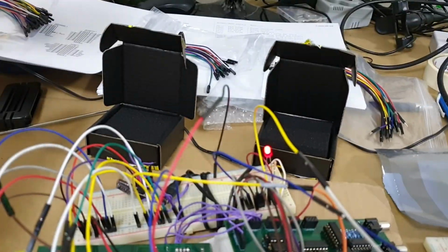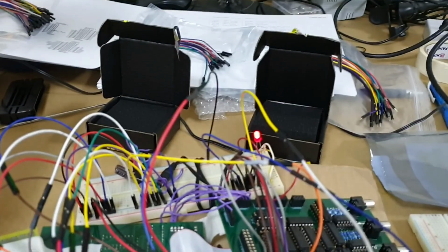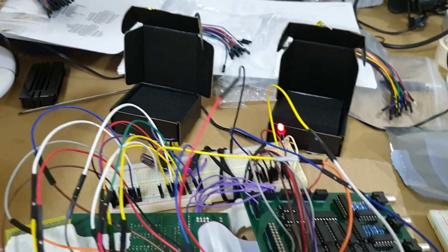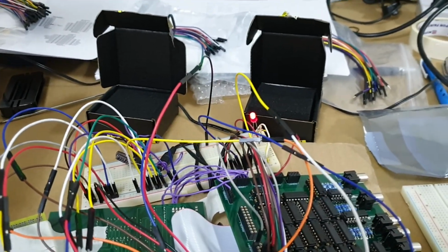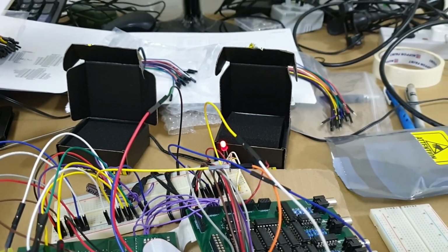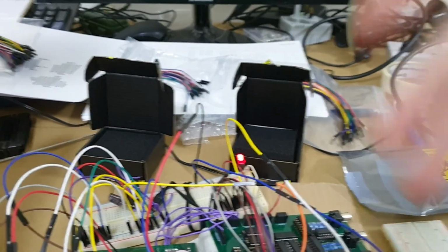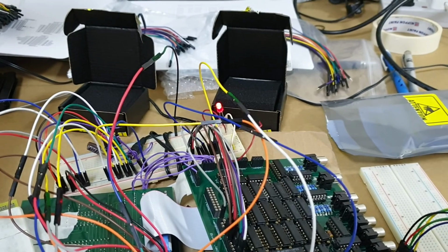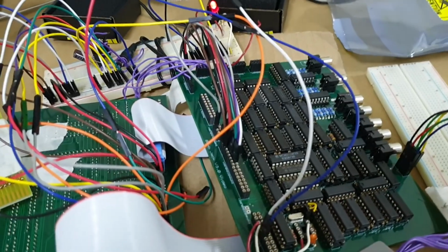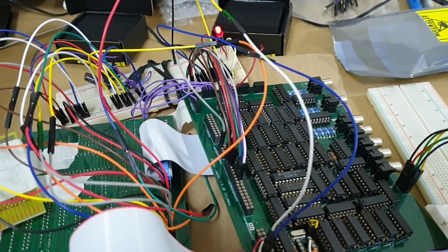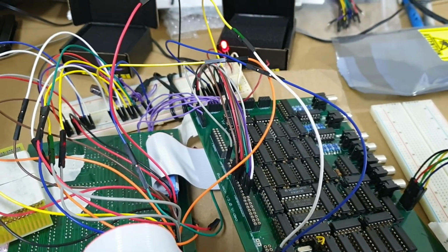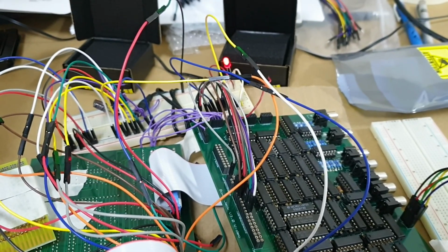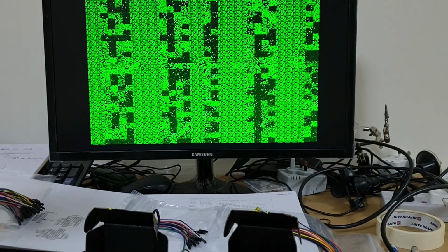The Commodore 64 user port, as a prototype on the breadboard, I will use the logic analyzer to make sure that the signals are correct first and expected, and then it should just be a very simple case of connecting the output signals straight into these headers here, and then just repeating the test from Commodore 64 that was verified by the logic analyzer, and then just seeing everything work as expected.